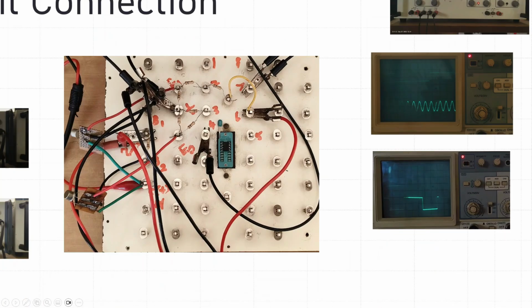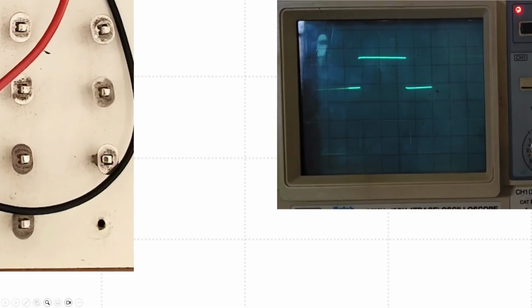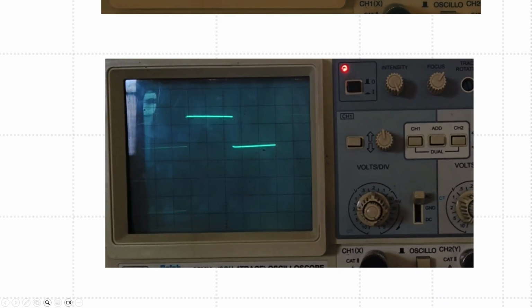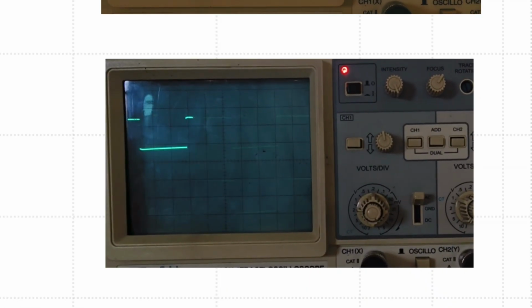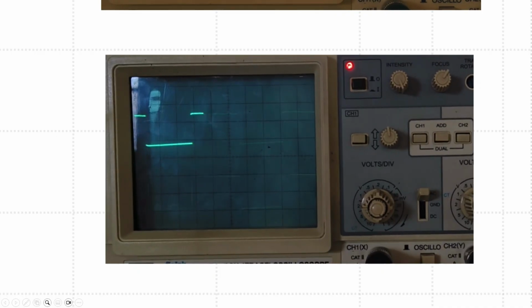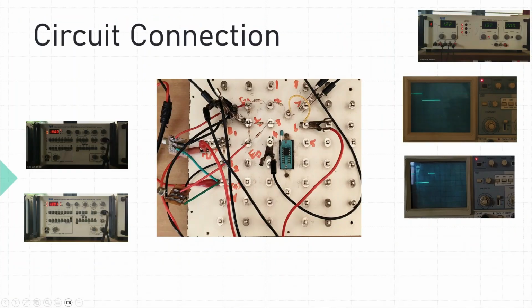In the same way, you are going to see the message signal that is recovered when you connect the demodulator or detector circuit. This is the T on of the recovered signal, and this is the total T, that is 10 milliseconds. Find the error between these two and find the message signal frequency.